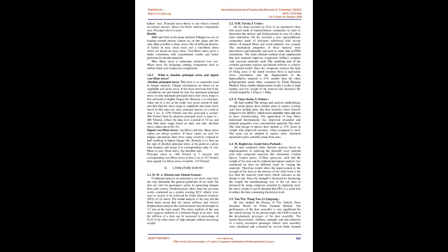Poisson's ratio. Poisson's ratio is defined as the negative of the ratio of lateral strain to axial strain for a uniaxial stress state. If a tensile load is applied to a material, then the material will elongate on the axis of the load. Conversely, if a load is compressive, the axial dimension will decrease. If volume is constant, the corresponding lateral contraction or expansion must occur. This lateral change will bear a fixed relationship to the axial strain. The relationship, or ratio, of lateral to axial strain is called Poisson's ratio.